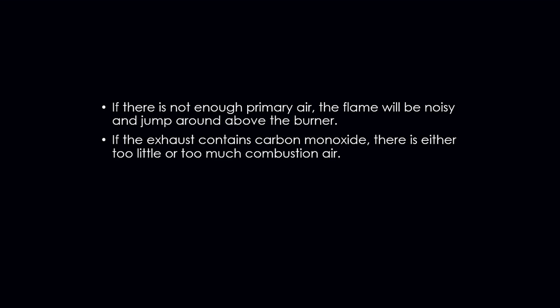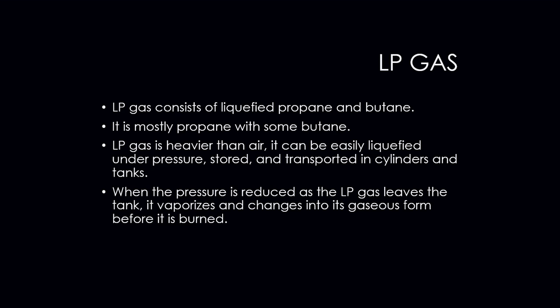If there is not enough primary air, the flame is going to be noisy. It's going to jump around above the burner. It's not going to be steady. If the exhaust contains carbon monoxide, there is either too little or too much combustion air.